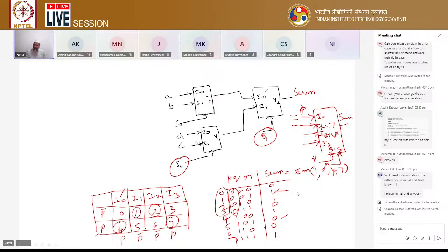This type of theory, how to implement a larger multiplexer in terms of smaller ones, I have already taught in the lectures. So in the given problem, this is the implementation of 4x1 using three 2x1 multiplexers. Then if you write down the equivalent circuit, the values of the inputs of the 4x1 multiplexer can be found out by using this table.